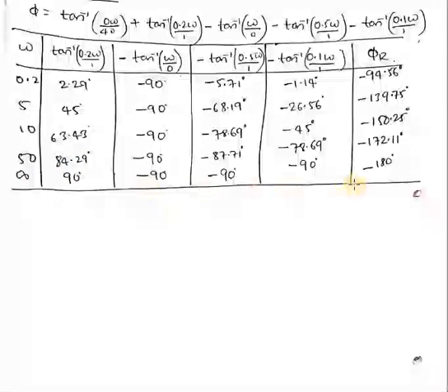at infinity only it is minus 180. So that means nowhere does it have an intersection with the 180 degree line. From that we can assume that our gain margin value will be infinite dB. And then you observe this magnitude line, and look for the intersection of this magnitude line with 0 dB. Wherever it intersects, from there you draw a vertical line down to the x-axis.